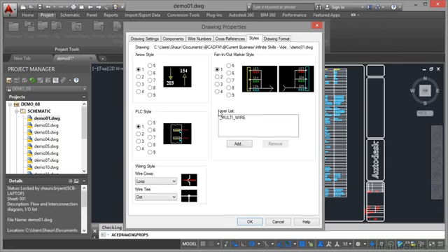Styles. This is very important. You've got arrow styles, PLC, programmable logic controller styles as well, wiring styles. If you've got a loop going across, one wire going across another, you can either have a loop, a gap, or you can make it solid. Personally, I always use the loop because it looks as it should in an electrical installation. You've got wire tees as well. When you tee one wire off another, you can use a dot or an angle or an angle 2. And again, I tend to use the dot. It just works as far as I'm concerned.